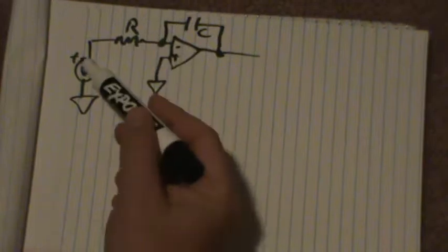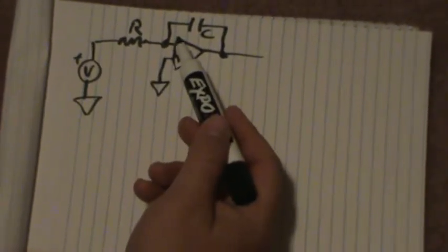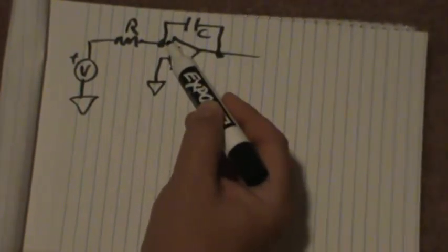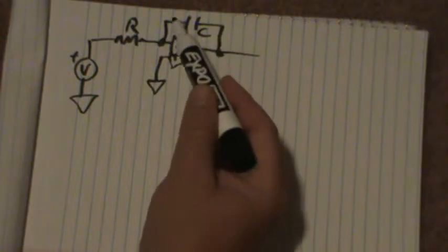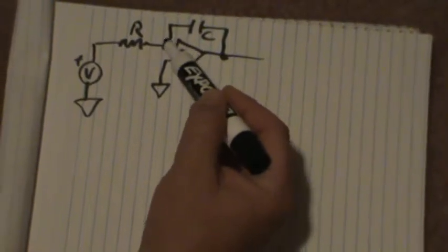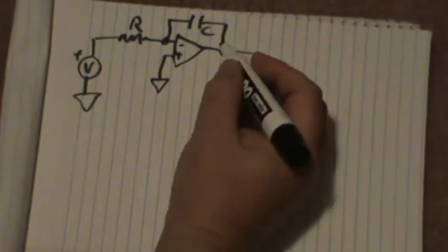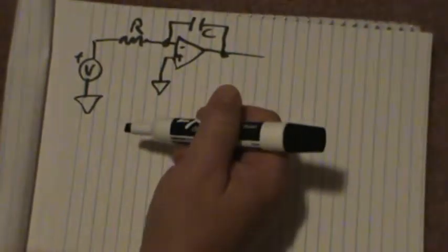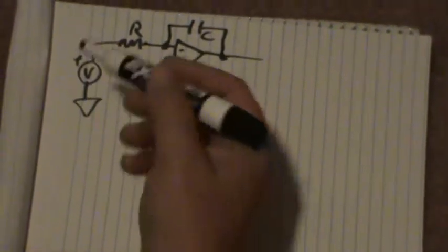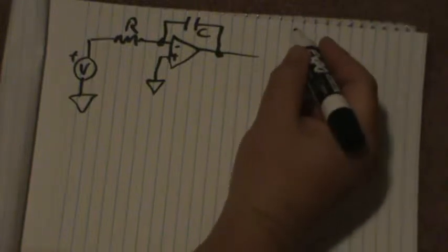Now if you think about what's going on here, my signal, my DC values, can come in perfectly fine and hit this negative input. My high frequencies cannot come back to get amplified though. Or I should say, actually, my low frequencies can't come back. The high ones can come back, and they get sent to ground, so they get killed off. In essence, the high frequency ones are going to get damped out on this negative feedback. The low frequencies are not. So low frequencies will be amplified, high frequencies will be killed off. That makes this a low pass filter. So this is low pass.